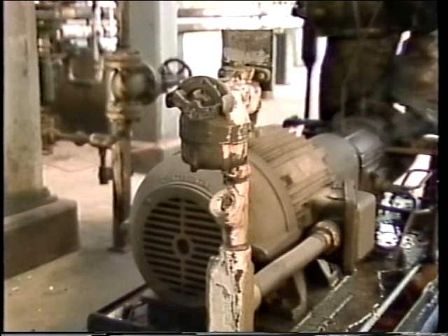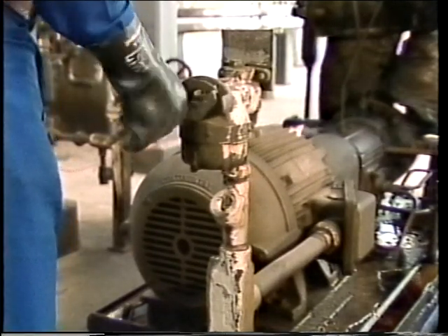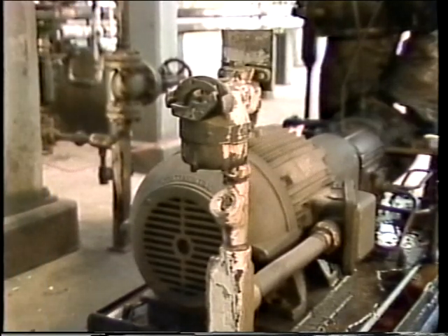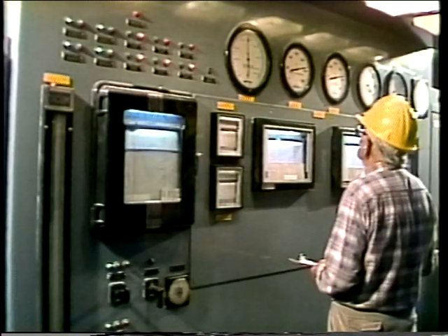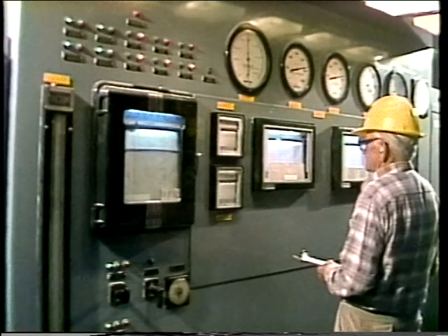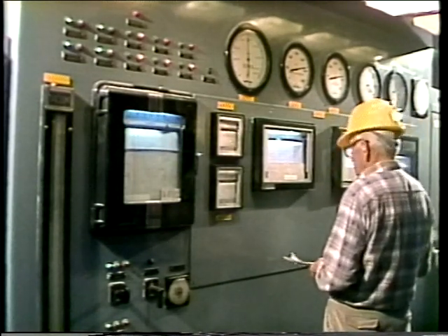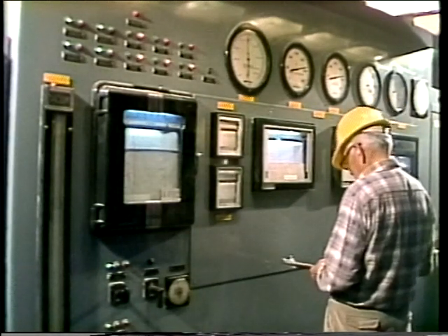On some machinery, the operating speed cannot be controlled. In these cases, the machinery is normally designed to operate at speeds greater than or less than the critical speeds of its components. On machinery where the operating speed can be controlled, safe speeds are normally specified by the manufacturer. In addition, operators are usually taught to avoid operating rotating equipment near its critical speed.